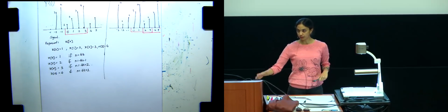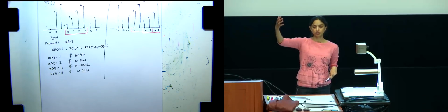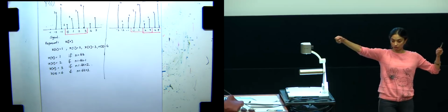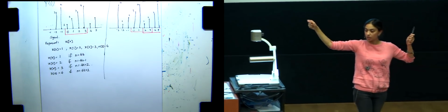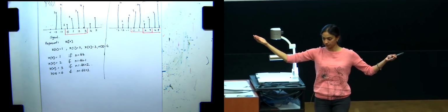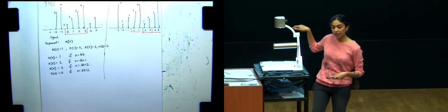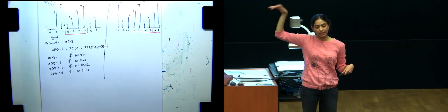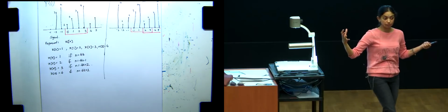And so this is something that we're not going to be able to disambiguate. But thankfully, because we are the engineers that get to design our locationing system, we will be able to design it so that we're not going to run into this issue. In fact, what you will do in the lab is design a periodic signal that is so long that the maximum shift you're going to get because of the distance is always going to be shorter than the period of the signal. So in a GPS system, the codes that you use, the periodic signals, are very, very long. In this setup, if I told you that your maximum delay can be 3, then can you tell me exactly what the delay was? But if I don't tell you that extra piece of information, you cannot disambiguate.